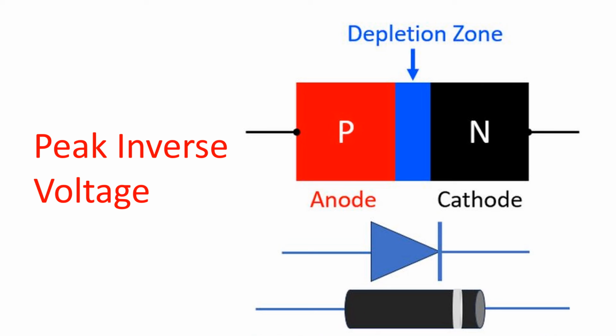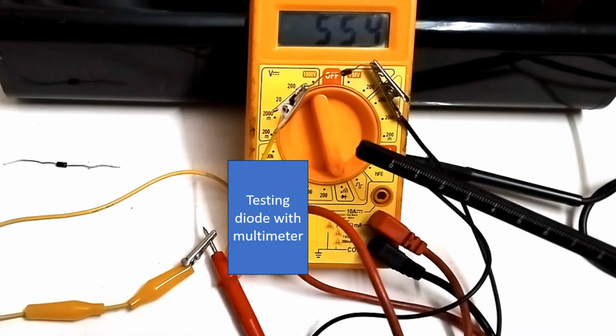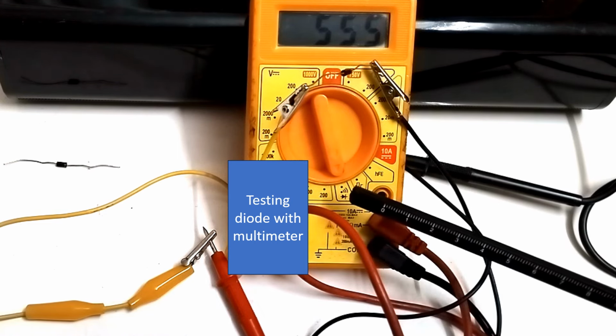So that is where this peak inverse voltage comes in. If the peak inverse voltage is low and you are applying a higher voltage of alternating current to the diode, then it will break down. For testing a diode, you have to choose the selector switch in such a way that it indicates the diode symbol. That is how you test it.